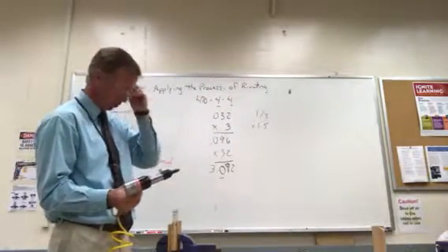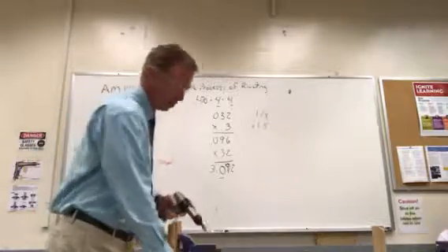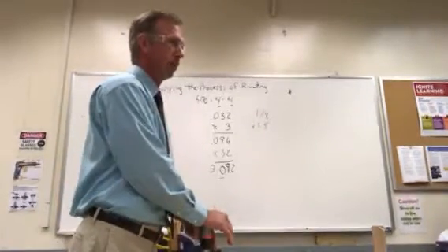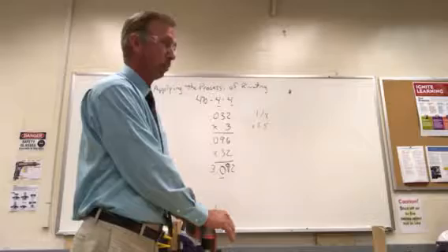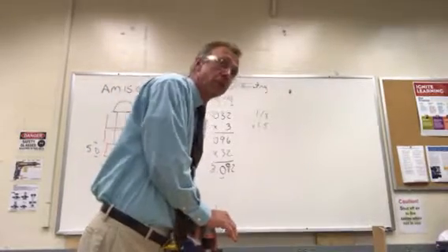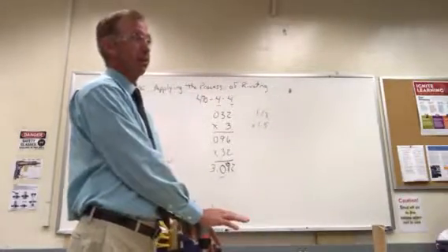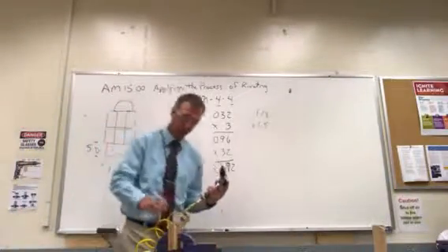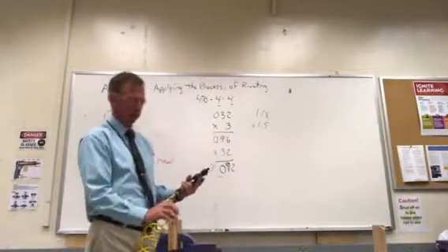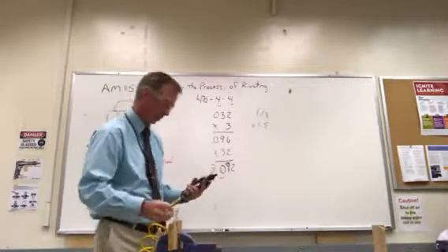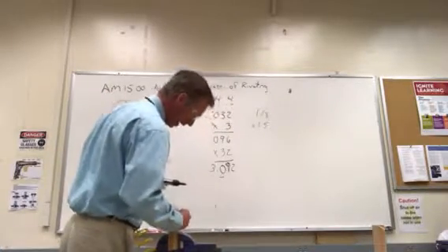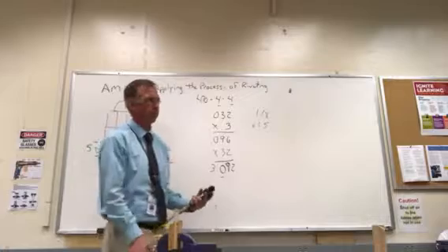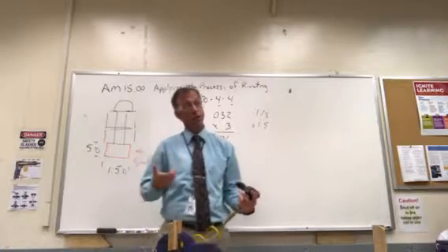Safety glasses, I want to slap some safety glasses on there. Check the air pressure. Is that good? Yeah, that sounds good, because all we're going to do is just pop it, and that's going to be it. Okay? All right, now, what kind of rivet are we working with? So I know the measurements, I know the length and everything. Good, I've got a button head, a universal head.